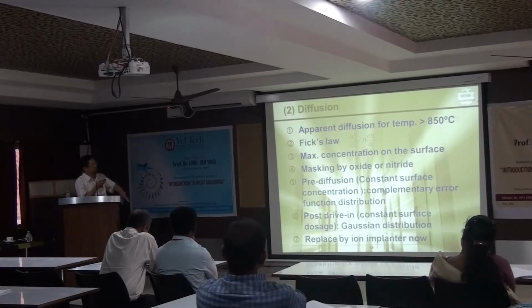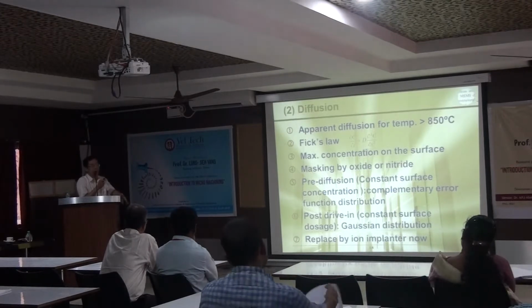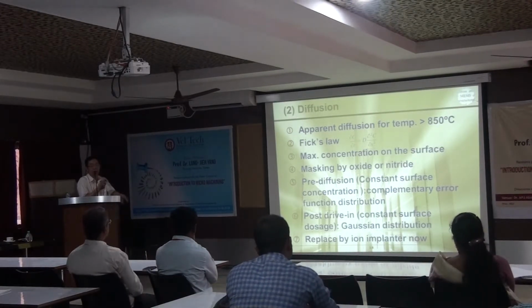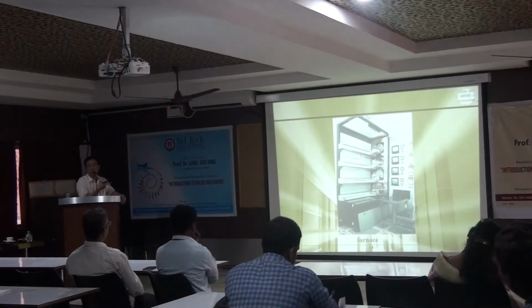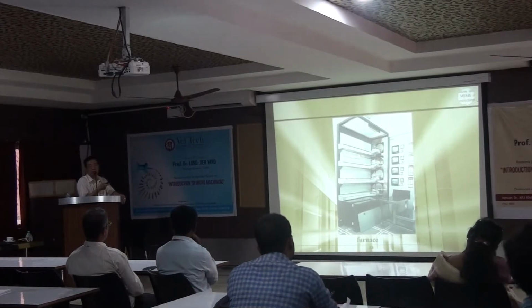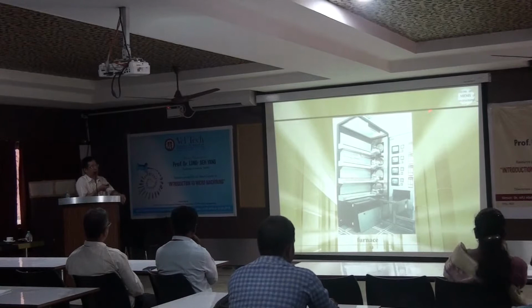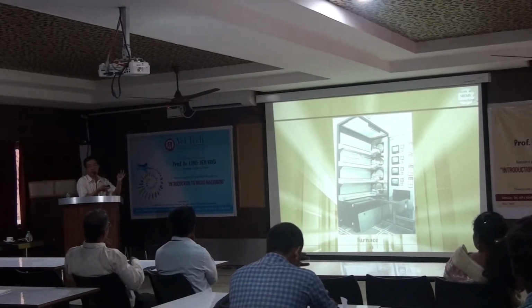The second process I want to talk about is diffusion, because diffusion uses a similar machine as the oxidation. The machine is very similar to the oxidation furnace, but with some differences. Oxidation only feeds the gas with oxygen or water vapor.